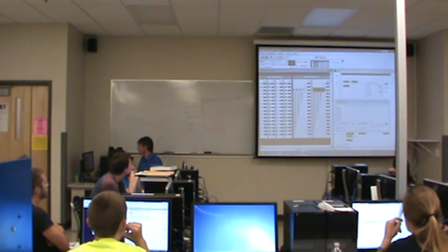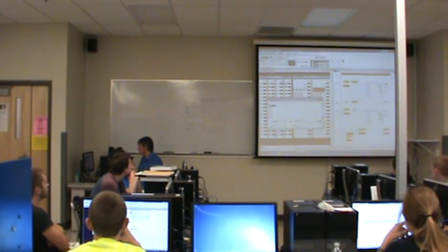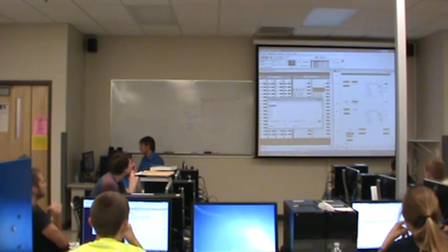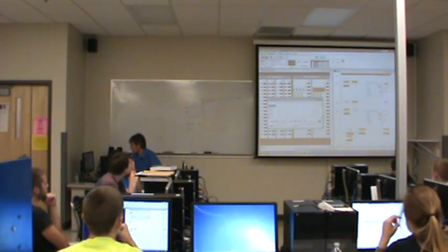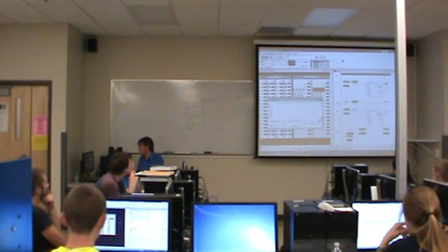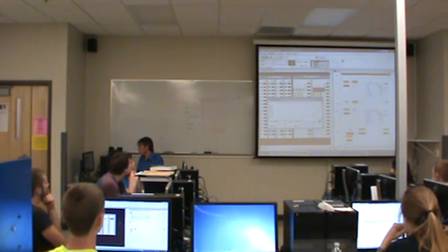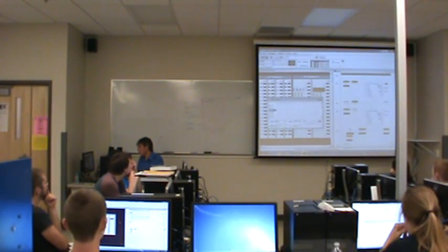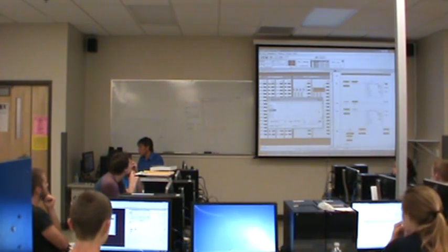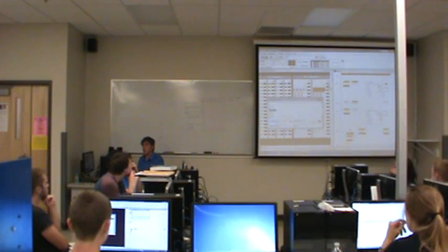So what does it do? Well, it takes sequence output, or tells sequence output to go to the next step. Sequence output hadn't done anything yet. But now that it's been triggered, sequence output copied B3:11 to output 6. Now notice there's a 1 there, so it put a 1 in place. Okay.